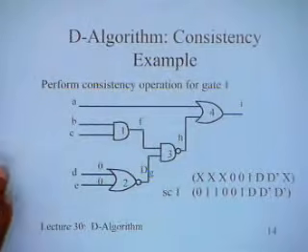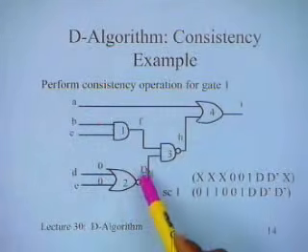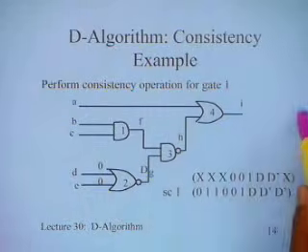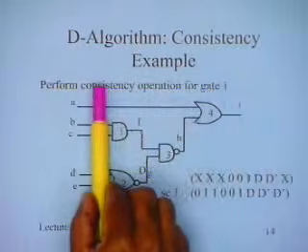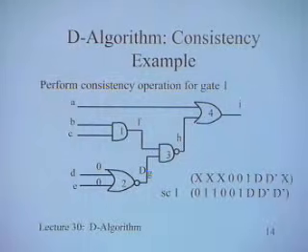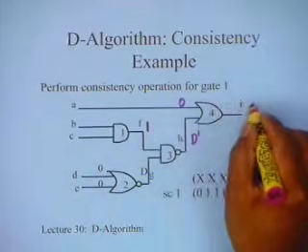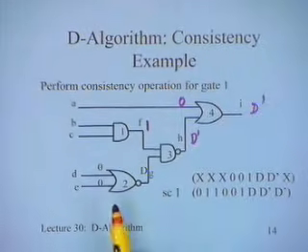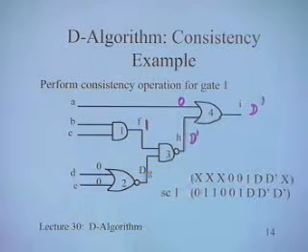Look at all the unassigned gates. Here you went from the faulty node to the output, but now you have to go back. That is what is called back propagation. Look at the output. In this case this was 1, this is D complement 0 D complement. So I have this 1. Now I will not look at the PDC, I will look at the singular cover. I only have to look at the truth table, I do not want to bother about the faults now.